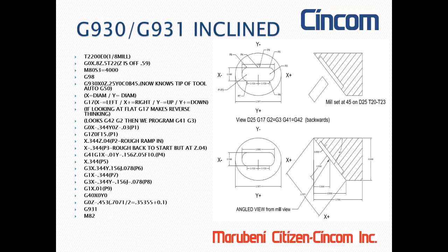Here's one more. Just to verify, the D25 is full 5-axis capable, but the L220 with the tool changer is not. Yes, this is correct. Our M70 and our L220 with the tool changer are 4+1. Any 4 axes can move simultaneously, and then we have 5 axes total. So you can choose any of the 4.